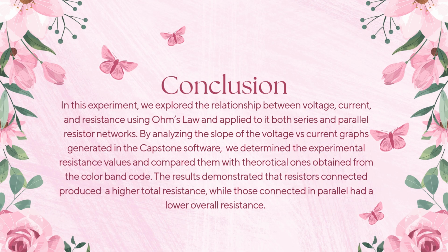In contrast, a parallel circuit lowers the total resistance since the current can be split and taken into multiple paths. In series, the resistors are connected end to end, so there's only one singular path for the current to travel. Like if it was a long road with 3 toll booths in a row, the current has no choice but to go through every resistor, end after end, and it adds to the total resistance. So it's harder for the current to flow, and it makes the resistance higher.